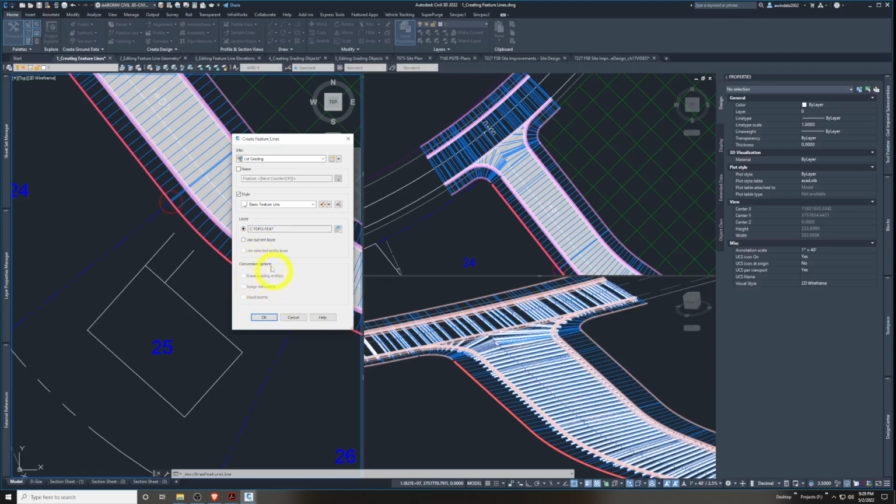So in this case, these will be options if we created the feature line from an object, but we're creating this from scratch. So these are not objects, these are grayed out at this moment. If we create it from an object, which we will later, it gives you the option to erase the existing entity you're creating it from, which would only be overtaken by a feature line. It gives you the option to assign elevations, which we'll later see, that you can tell it to be plucked from any surface in the drawing or a very specific elevation, static, maybe just all 3000 for whatever reason, or a relative elevation to a surface plus or minus an amount. And it also gives you an option at the end to weed points.